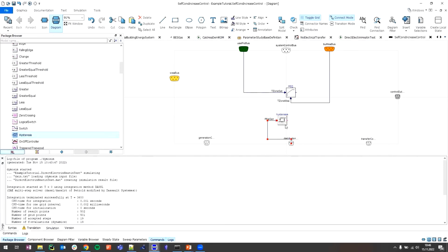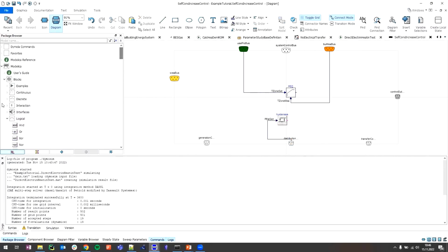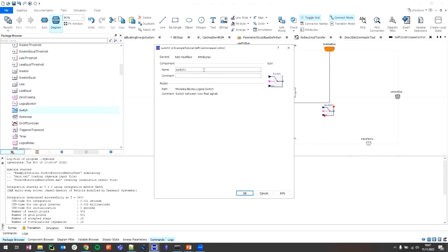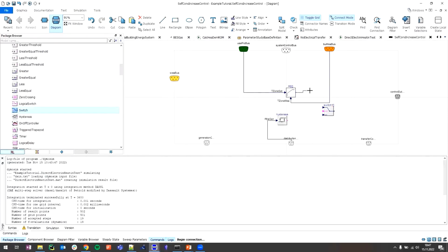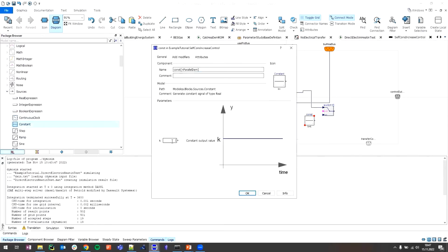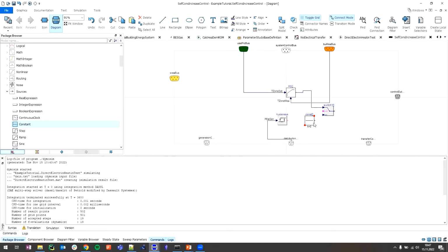Just a basic hysteresis to prevent frequent switching. Then we say we are only going to use this output if this is true. This is an array output, so I'm going to make the switch an array as well. If we don't use the PI controller, I'm going to add a constant 0 block, which again is also an array, which is 0, final, and each.